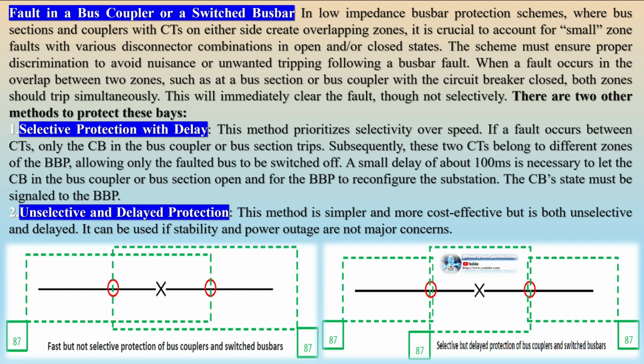Double busbar with transfer bus. To ensure selective busbar protection, position inputs on each disconnector and circuit breaker are required. These inputs help select the correct differential current measurements for different zones and achieve proper busbar splitting during faults.